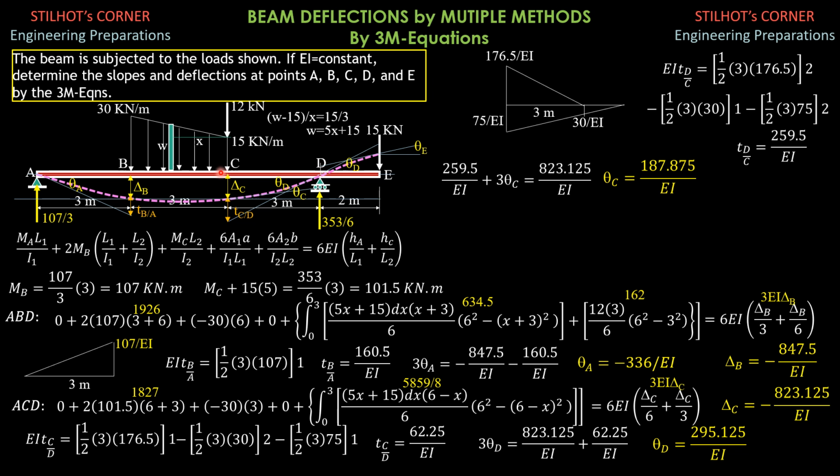So it will not bend the beam AC, in other words. So that's why there's no value PA over L, quantity L squared minus A squared. There's also no value PB over L, quantity L squared minus B squared for that load. It acts as the support. Then for portion CD, there's no load, so that's why it's just 0.